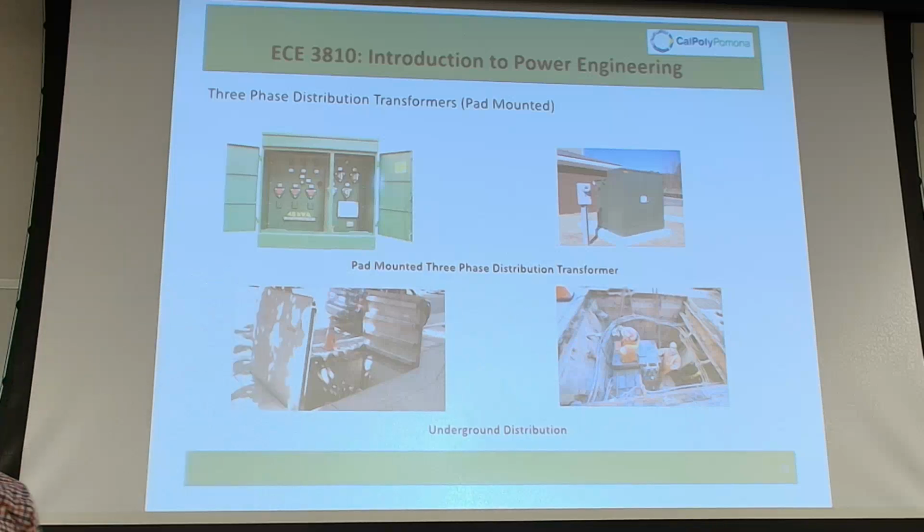But these ones, you see them around probably. You see these green boxes just sitting. I think there's a couple here if you go around. Those are what we call distribution pad-mounted transformers. These are not single-phase. It's not economically feasible to build single-phase pad-mounted transformers, so they're mostly built as 3-phase. And obviously, with 3-phase, you feed more customers with one transformer than with a pole-mounted one, right? So it's a higher capacity. These ones are usually 1 MVA,